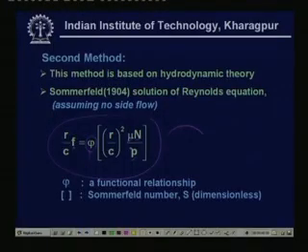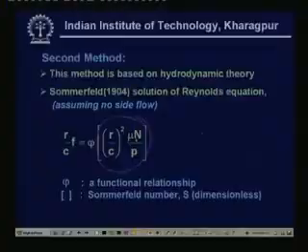Okay. So, this idea is utilized by Raymond and Boyd in their solutions. So, what is that? This bracketed term is called the Sommerfeld number S, which is a dimensionless number. Here you can see this is the bearing characteristics number we have already discussed earlier. This is inbuilt in the Sommerfeld number.